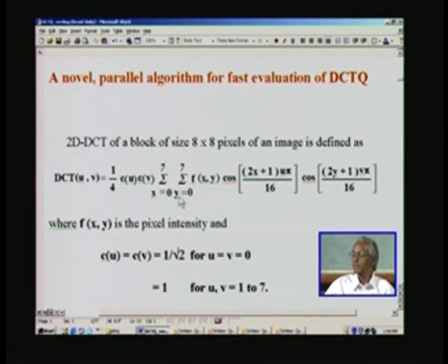Then the sigma covers summation over all, and if you apply it for this term alone, it simply implies the summation of all the pixel intensities. To keep it simple, let us deal with only one component, or just plain monochrome. If you are processing color, we are dealing with only one of the components, either Y or CB or CR.